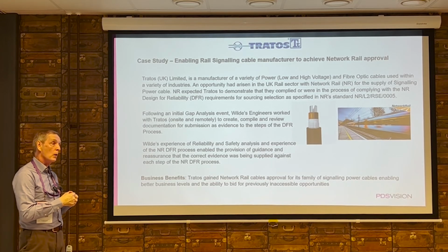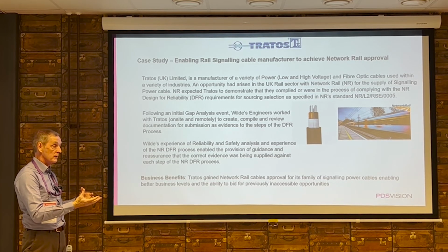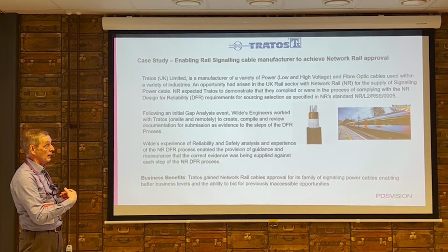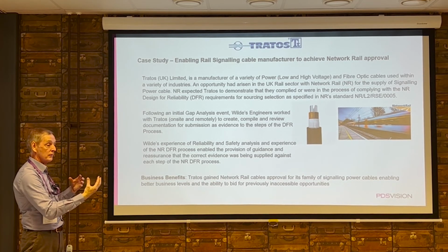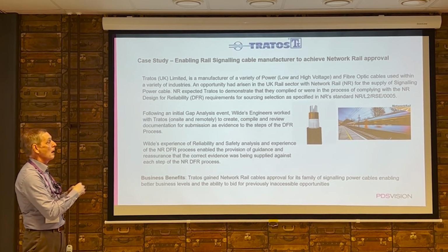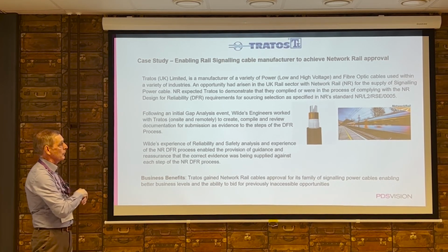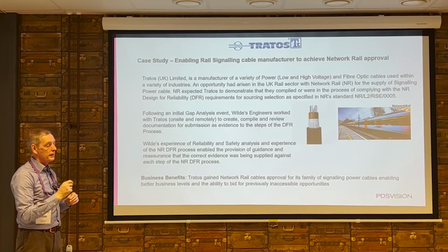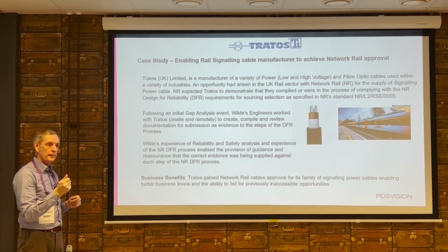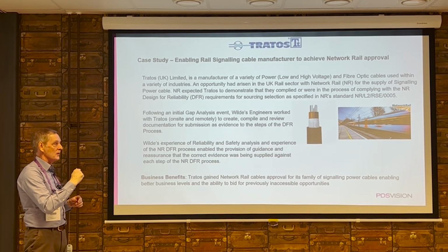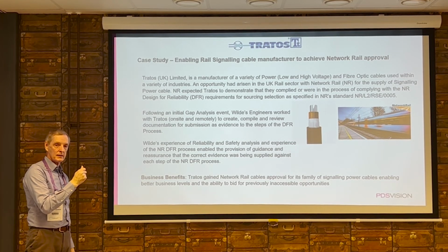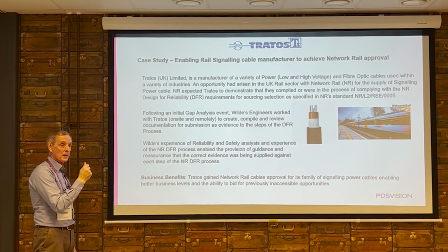They called upon Wild to develop a process for them to follow, and then for doing the calculations so that once we've been through that once, they can do it themselves thereafter. But when we did the FMEA for the cable, the most significant cable failure is rats. And that goes into your FMEAs because rats bite the outer coating for your cables. And that's one of the biggest failure modes.